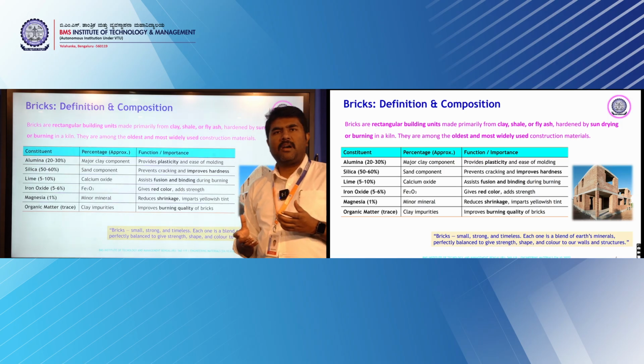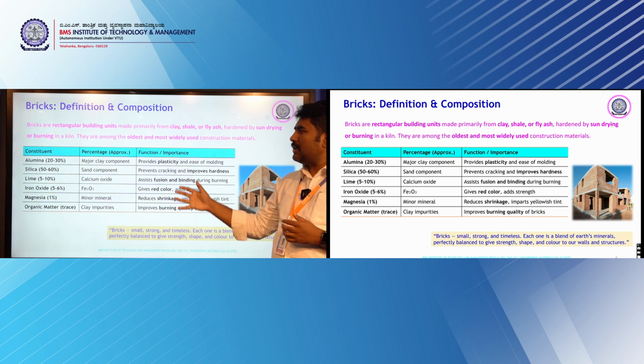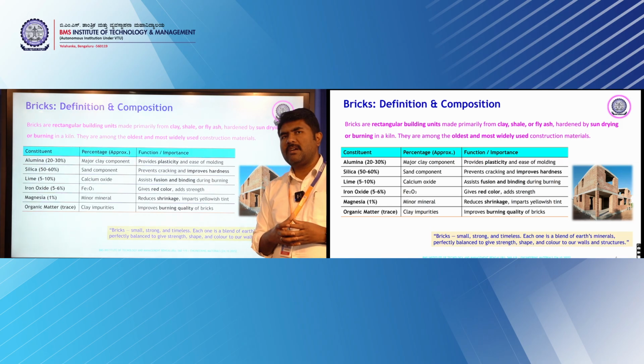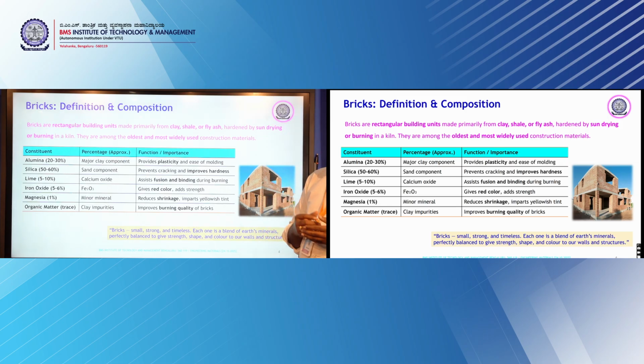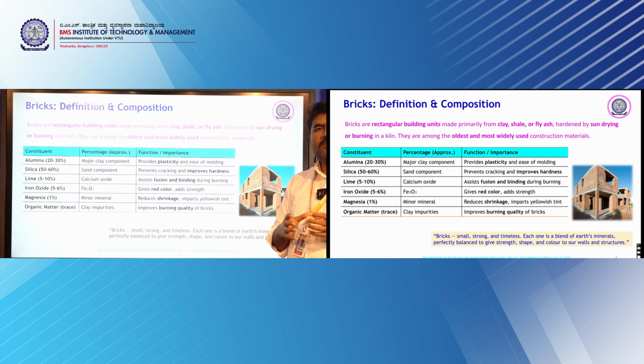No. That mud has to be first separated from all the debris and other things, and we have to check whether this limited composition is present in that mud, so that it can be molded further. It has to be mixed with water and other ingredients, and then molded. After being molded, it has to be cured, dried in air, and then burnt. We have to check whether the mold is stable enough to burn inside the furnace and come out as a proper brick or not.